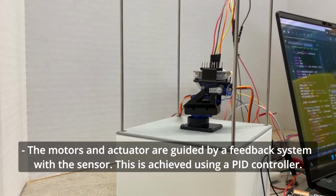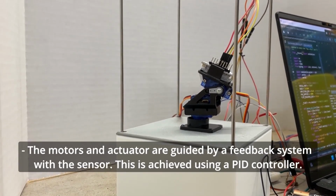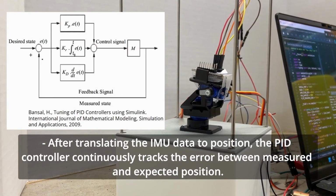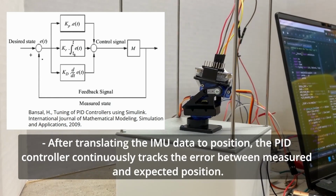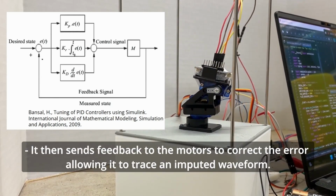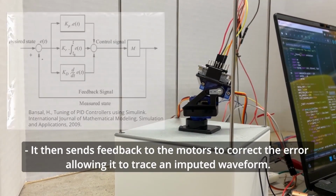These motors and actuator are guided by a feedback system with a sensor. This is achieved using a PID controller. After translating the IMU data to position, the PID controller continuously tracks the error between measured and expected position. It then sends feedback to the motors to correct the error, allowing it to trace an input waveform.